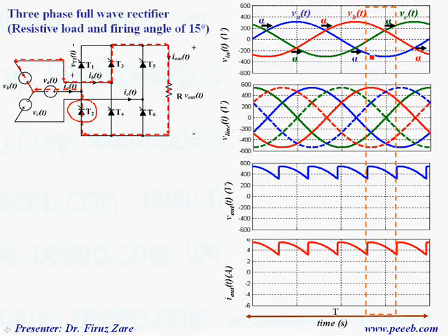That means beyond this time phase A appears at this point while we still have phase B on the positive terminal. So in this case we have line voltage VBA across the load, which is this voltage, VBA.